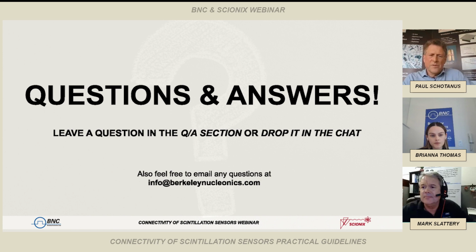Well, let's click this one away first. Usually when pulses have long decay times, they also have pretty long rise times. And when you are integrating in a preamplifier, there are cases where you integrate the information away and you don't see anymore what is hidden in the signal of the scintillator. So it depends a little on the material, and also on the integration time of your preamplifier.